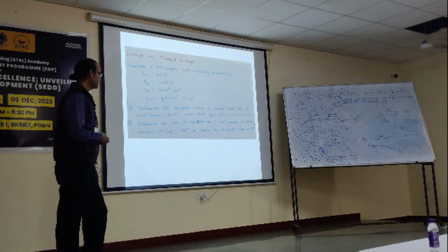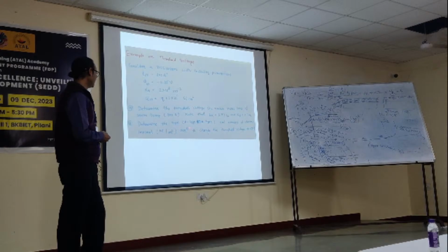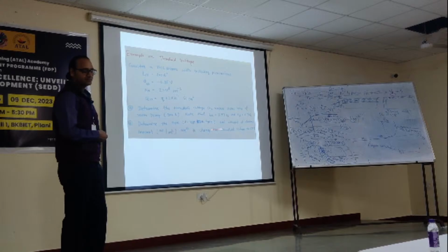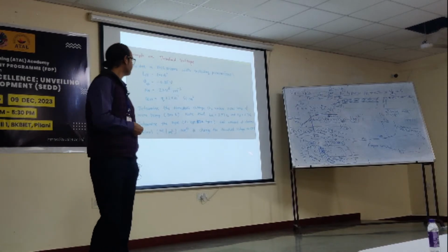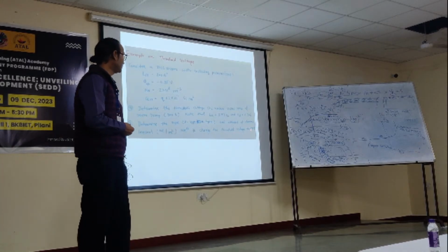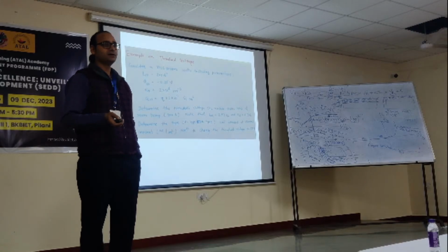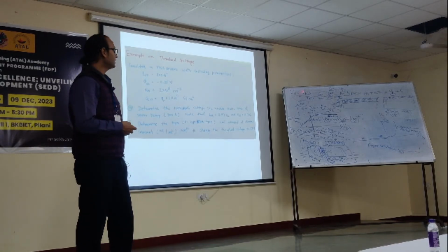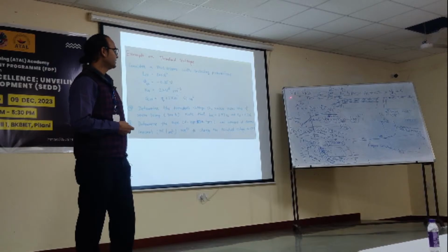And then there is a cross question: you have to determine the concentration that is required for a threshold voltage of 0.8 volt. So how will you get that? You are given Vt, you are given phi ms, you are given this also, and now from where will you get the value of Qd here?